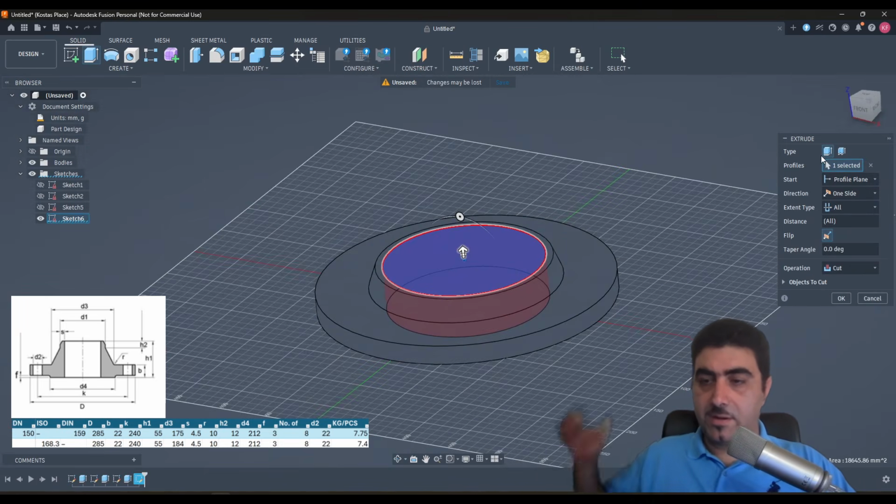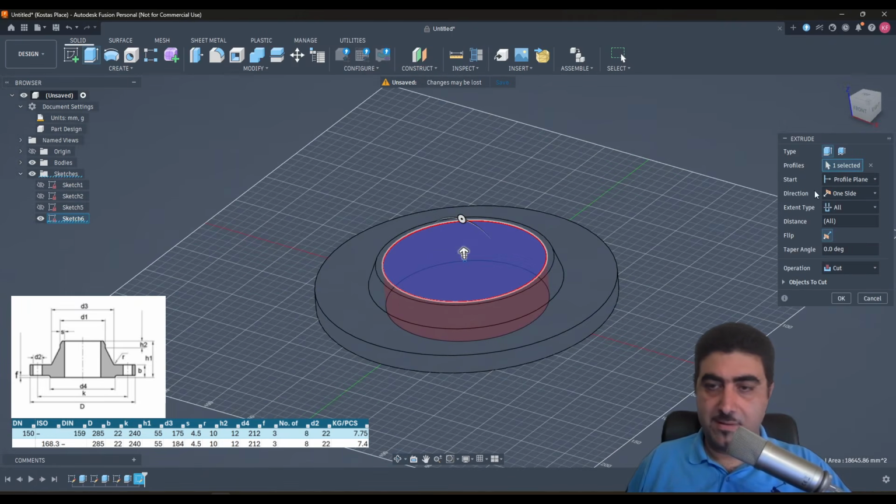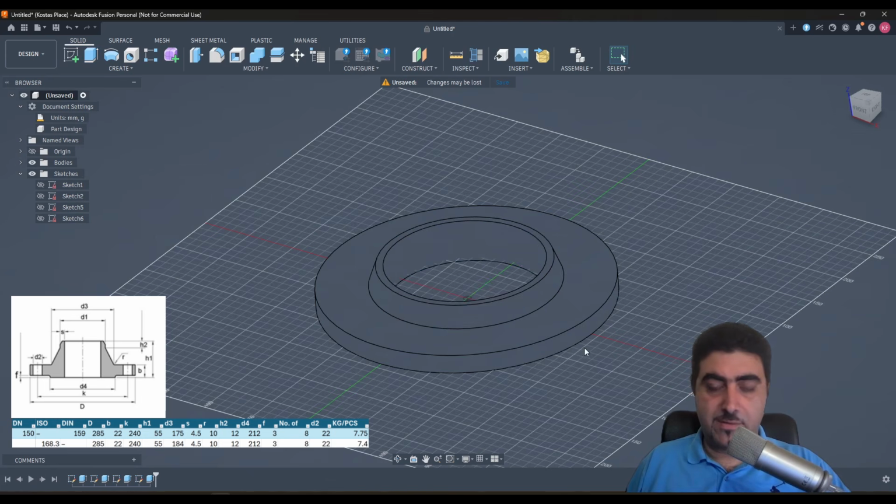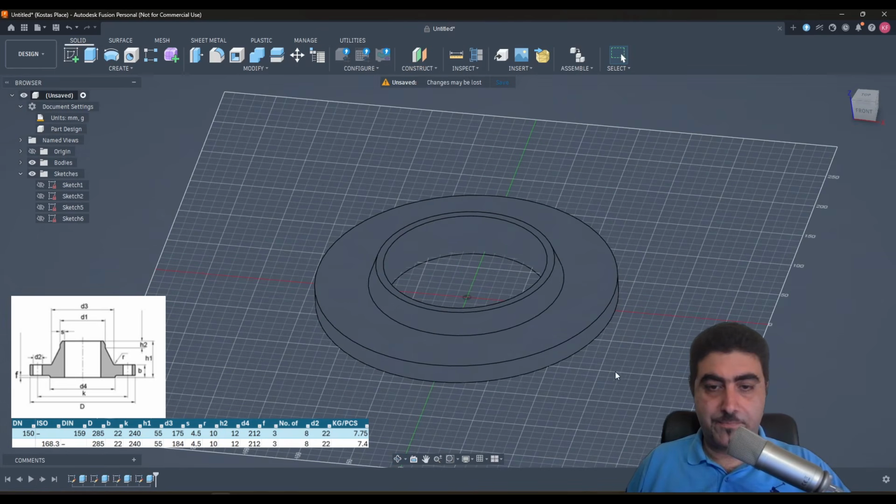Okay, so cutting and adding material is the same in Fusion. It's the same as in Inventor. You can still change the operation, whether it is cut, join, or whatever, but it is here, and you can choose to ignore bodies with your cut or whatever. Okay. Oh, cool.